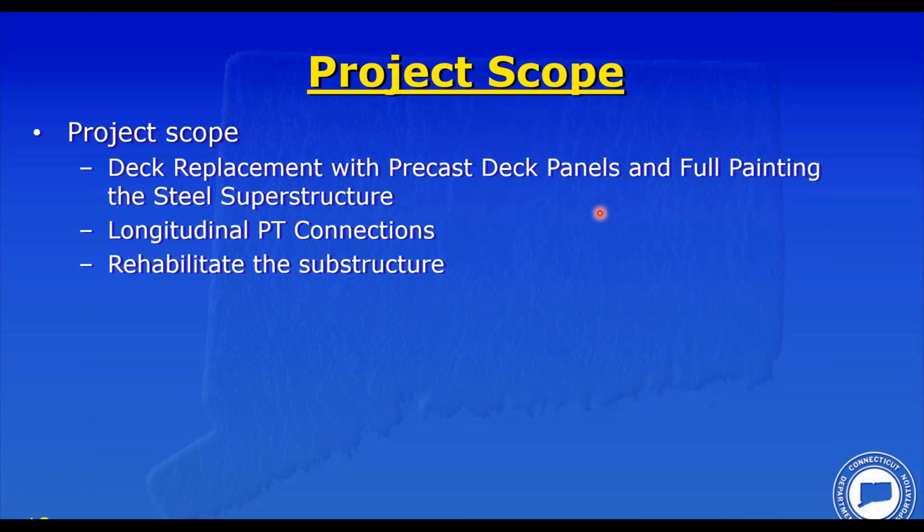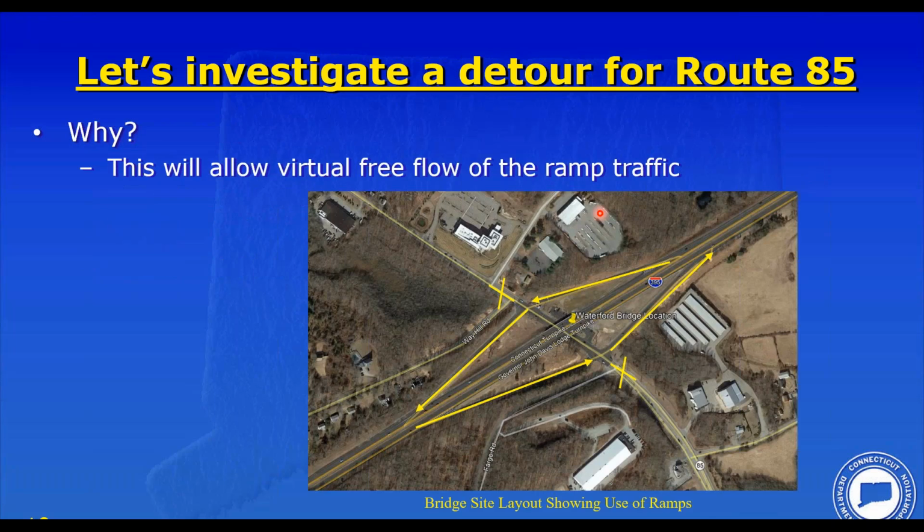We decided to use details very similar to what we showed you from the 1990s of longitudinal post tensioning for the connection of the decks with grouted joints, and then rehabilitation of the substructure was also in the cards for this structure.